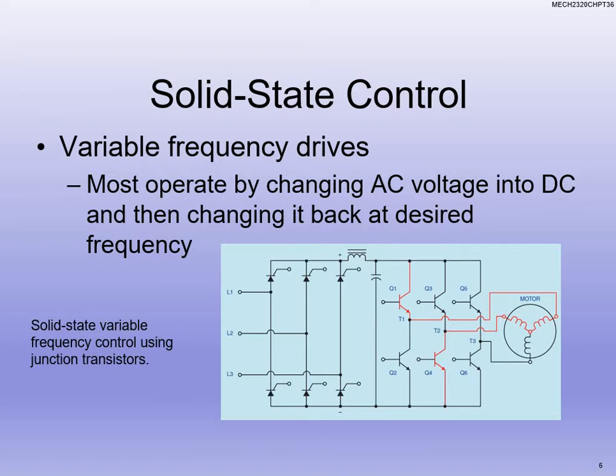Solid state control is really everything that we're talking about, with lots of use of different types of transistors. When we're looking at a variable frequency drive, the majority of them take an AC voltage and turn it into DC, and then change it back at the desired frequency. It's not necessarily changed back into AC, it's changed into kind of an alternating DC, and most of the motors can handle it.